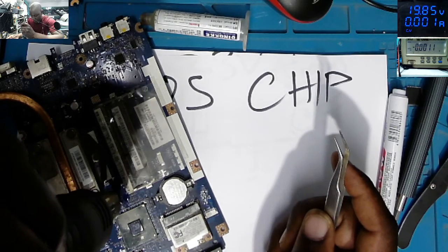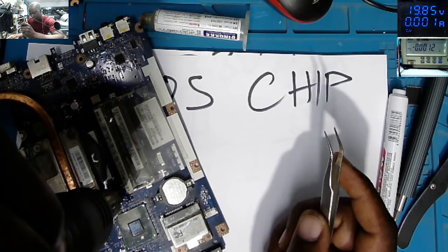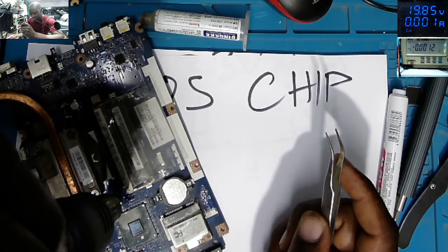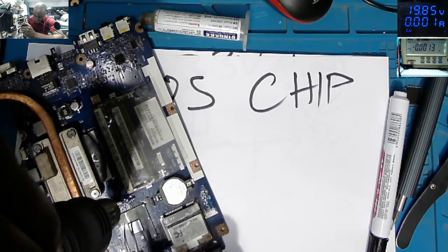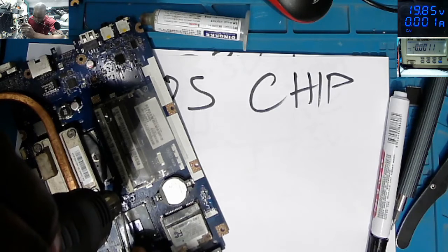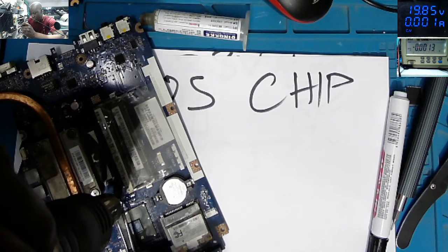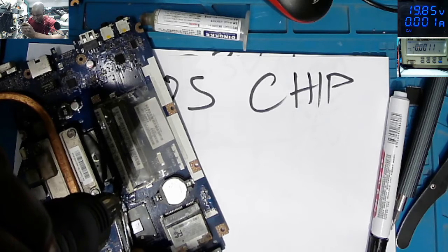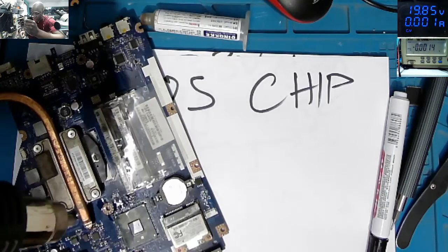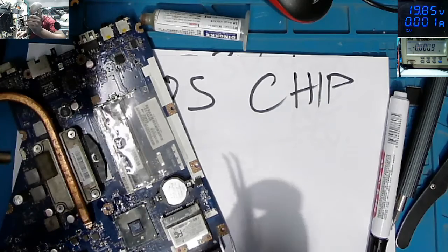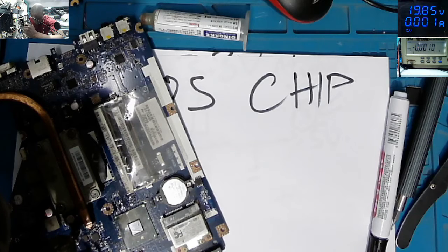Because you have to know, on motherboards you find either one or two BIOS chips. They are the BIOS for the EC chip. You can get the BIOS for the PCH. I took out the BIOS. I also need to take out a MOSFET, just a random MOSFET.